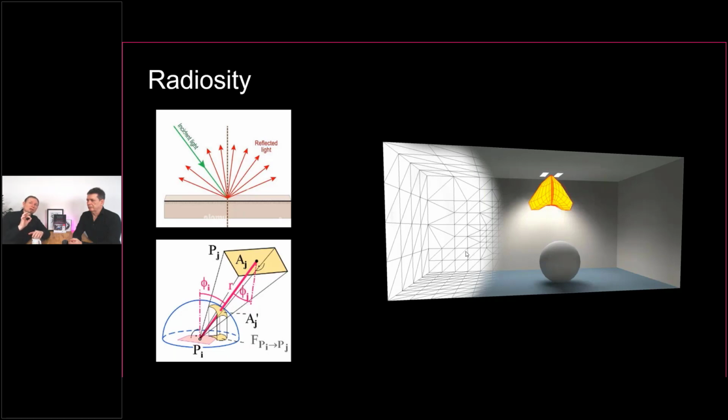You can also say, okay, I do not want to have these automatic patches on the indirect part. You can say, okay, I want to have it really detailed. I want to have small patches for the indirect part. This makes the calculation more accurate, but also demands more performance and higher calculation times. Normally RELUX will give you good settings for the calculation.